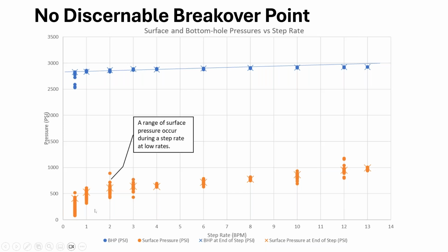But once you have established a consistent flow rate, the pressure increases gradually, and there's not a lot of variation in bottom hole data. So if you are reviewing and analyzing a test without bottom hole pressure data, it's crucial to understand that the pump itself is generating variation in the data, even at high pressures. When you think you have dialed it in, you may be going in a range, your pump pressure is all over the place, whereas bottom hole, it is not.